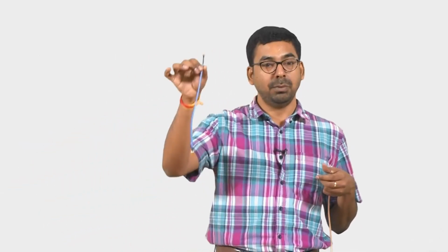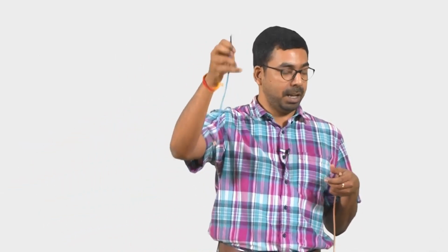There are also other things that we have. I have a different cable over here. It's an RG58 cable, a 50 ohm characteristic impedance cable. This is also a 50 ohm characteristic impedance cable. They come in different lengths, different colors, different composition. For example, the center could be made up of copper, or copper-coated steel, or it could be braided with aluminum on the top. The jacket material could be different in different companies. So, it just depends.